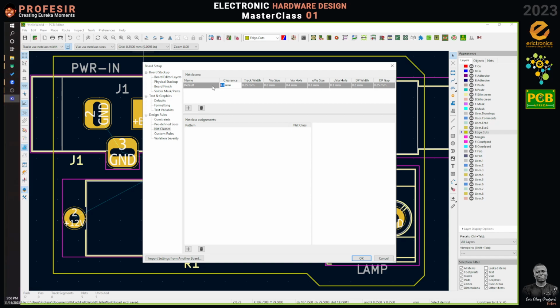Now, when we are developing the boards locally, you want to set this clearance as large as possible. Usually I use 1 mm, because I have realized that when you make it 1 mm, the traces print out nicely. You don't worry about short circuits and other things, right? Then the trace width. Like I said, I'll be showing you what the trace is.